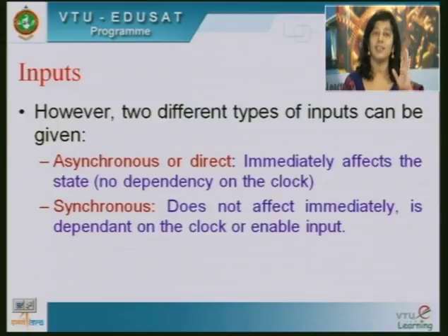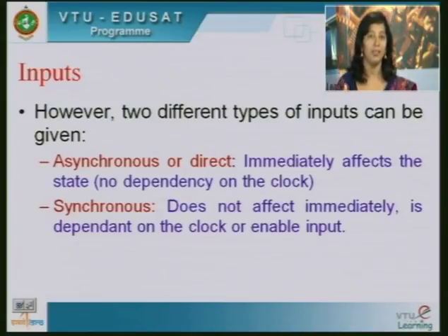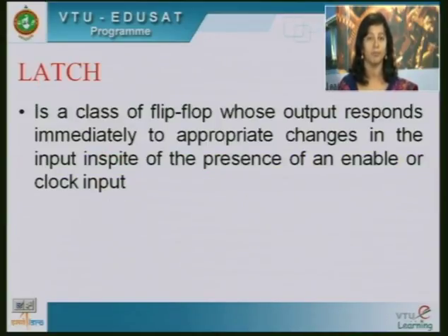So, either at the rising edge or falling edge of the clock, the samples of the input signals are going to be taken and the output will be computed. Till then, if it is not at those edges, somewhere in between, the output will not be computed till the next edge of the clock signal comes. So, we say it happens in synchronism with the clock, in matching timing with the clock. That is how you can give synchronous inputs.